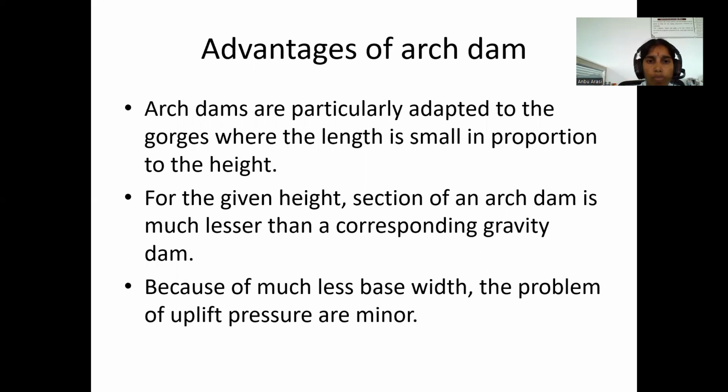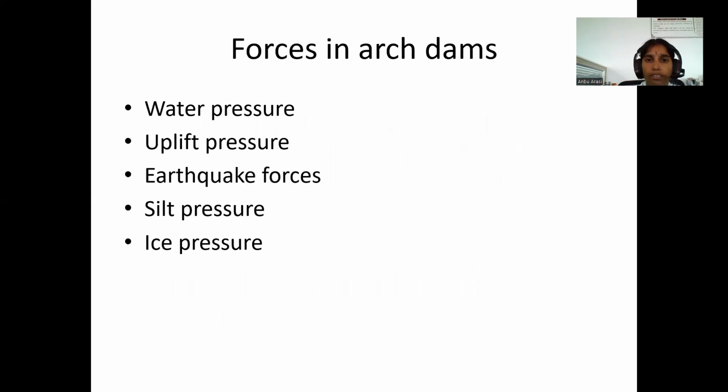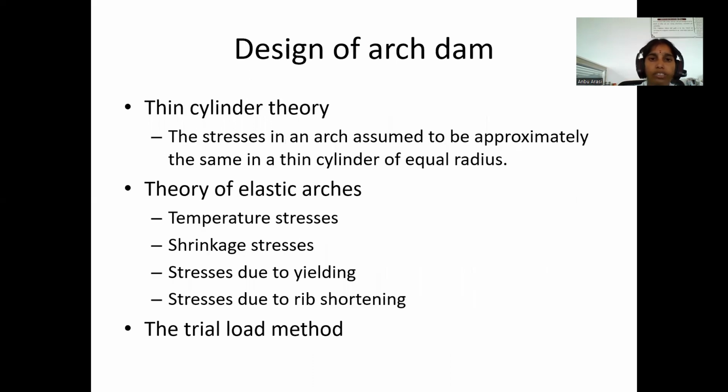Advantages of arch dam. Arch dams are particularly adapted to gorges where the length is small in proportion to the height. Because of much less base width, the problem of uplift pressure is minor. Forces in arch dams: water pressure, uplift pressure, earthquake pressure, silt pressure, and ice pressure.